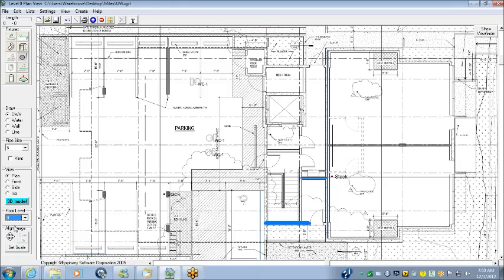And then when we go back down to the 0 floor level, we see our toilets grayed out, and we can use the line tool. And now when I highlight a stack, it's going to automatically draw a dimension line over to the reference lines. And I'll just use one right now.